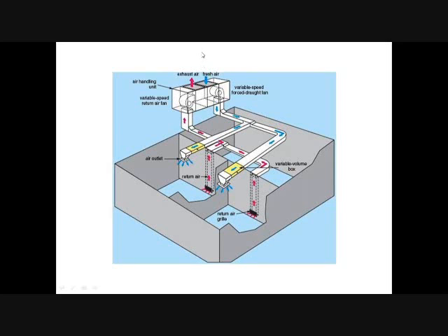Of course, the problem of getting fresh air is that, for example, in the summer it is very hot, it's 40 degrees outside. You want this air to be, for example, 20 degrees. It goes to the rooms and you get it back as, for example, 25, 27. And then when you mix it with fresh air, completely fresh air that is 40 degrees or 45 degrees, then you will need the machines to run more to cool it down. So you know, we need bigger machines.